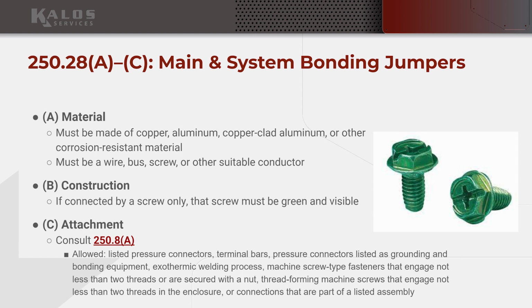There are some good reasons for the construction rules with ground screws, by the way. You'll notice that the thread count on a ground screw is 32. So 10-32, I believe, means 32 threads per inch. Correct me if I'm wrong. If you take the thickness of our box, which is maybe a sixteenth of an inch tops, we're required to have at least 2 threads engaged with the metal of something that we're grounding.